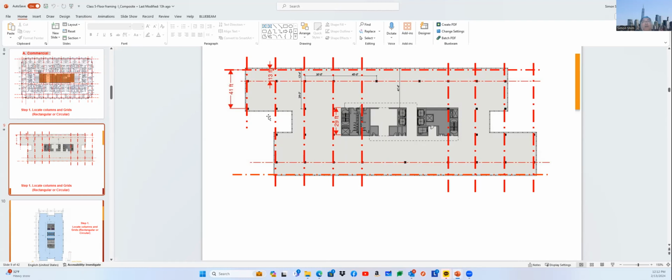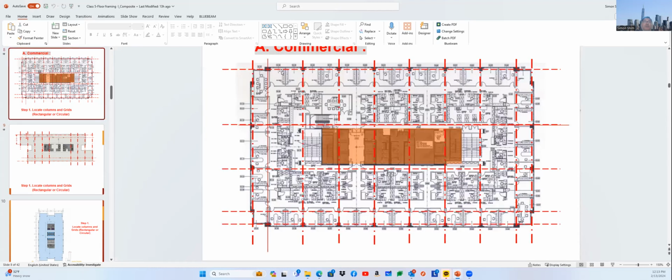And here, slightly different because of the building layout. The architect, I want something unique, right? They just make a notch at each left and right. Oh, what is this? But based upon this floor plate, we need to start laying out the columns. Initially, you could just draw the grid lines, and the basic 101 is that columns should be placed along the facade, right? Let me just go back to here. This column is placed along the facade, just close to the edge of the slab, right?